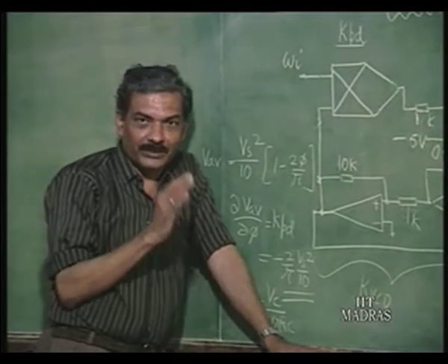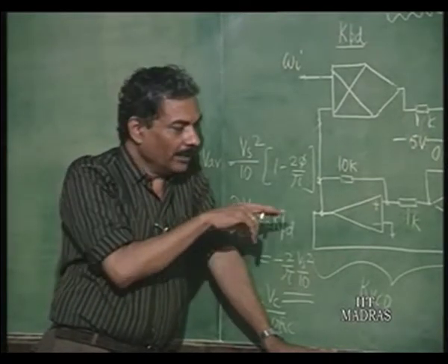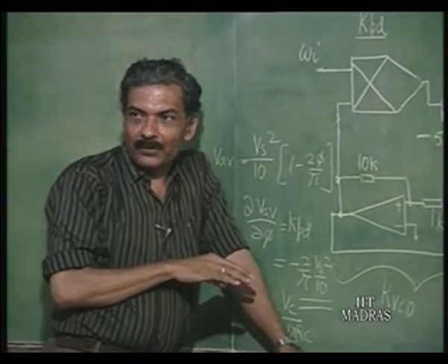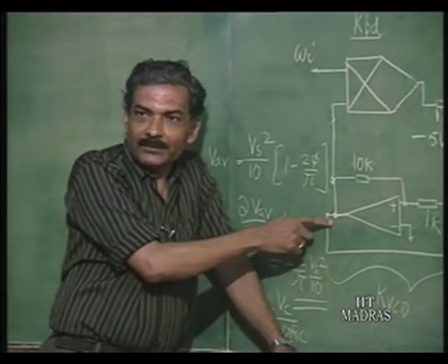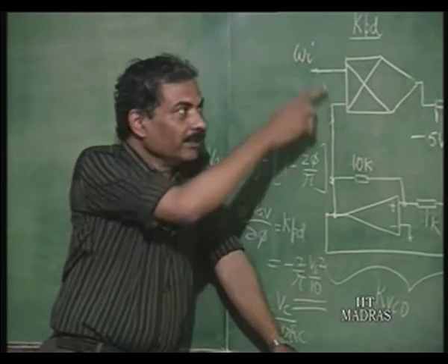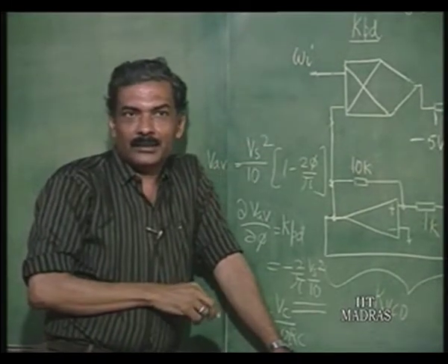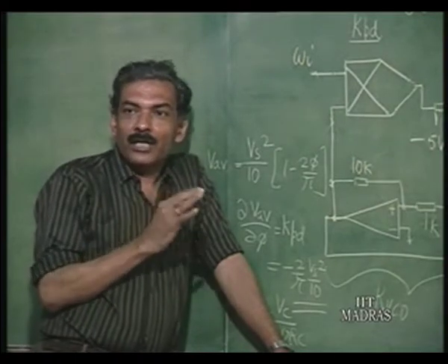In the oscilloscope, when you see this waveform, the one waveform only triggers the oscilloscope, and therefore we have made it such that it gets triggered by the free running frequency. So the input frequency waveform, which is seen on the other vertical deflection plate, is going to be not stable.